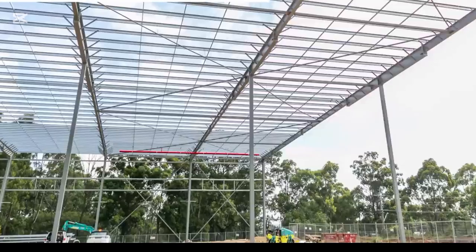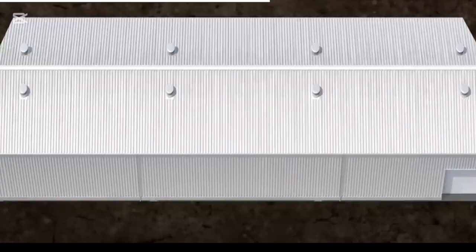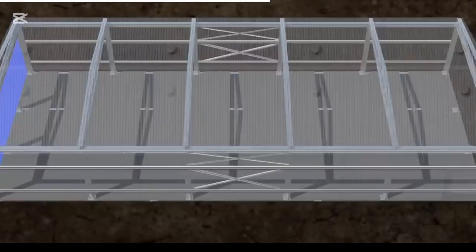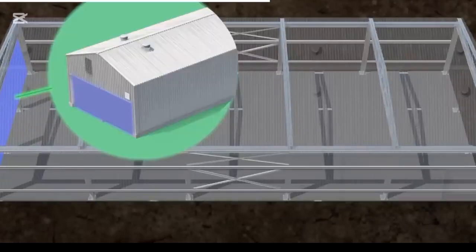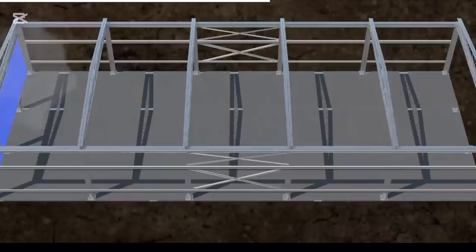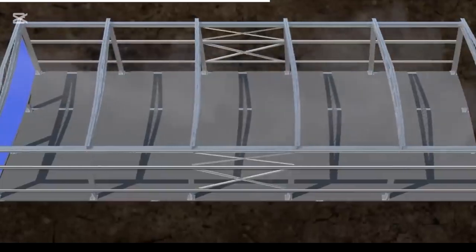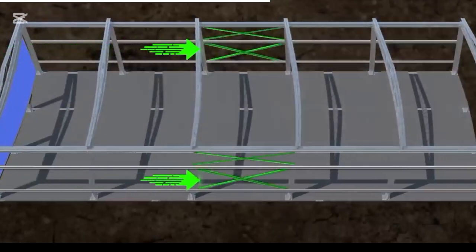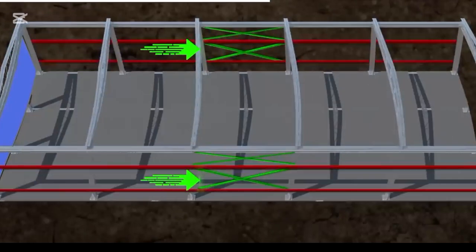Our previous examples of bracing have focused on its application vertically within a structure. However, these forms of bracing can also be used horizontally. To explain this, let's look at the example of a wide portal frame structure that is subject to a wind loading from left. Previously, our facade spanned across the entire front of the building. When wind loading impacted this facade and caused it to deflect, the force was transferred into the wall bracing via the tie beams located along the edges here.